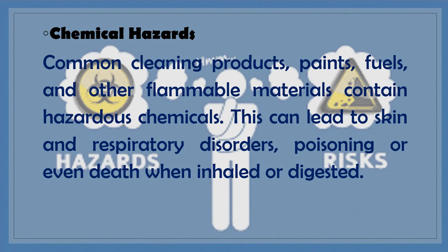That is why we do have different kinds of PPE or the personal protective equipment to be used in this kind of hazard. So what are the different kinds of PPEs that can be used if we encounter chemical hazards? So we can use gloves. Okay, so we can use overall, shirt or coverall. We can use eye protective shield, of course, para hindi matalsikan yung ating mata.